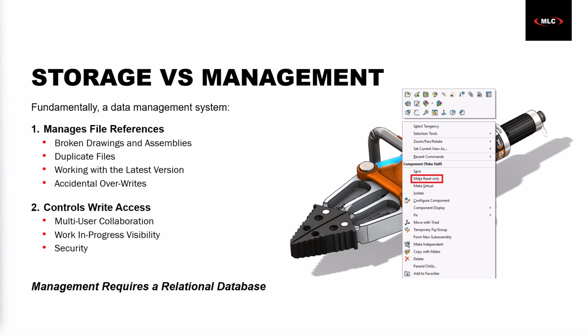Now, there are some tricks that all SOLIDWORKS users can take advantage of with its multi-user environment system setting, such as the option to toggle the read-only flag on files by right-clicking. And even without these setting changes, SOLIDWORKS adds some helpful functions to your right-click menu in Windows, such as Pack and Go, Rename, and Move to help manage file references. But you've got to be proactive to use these.